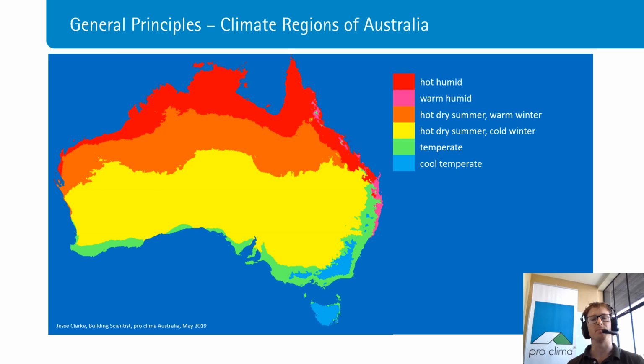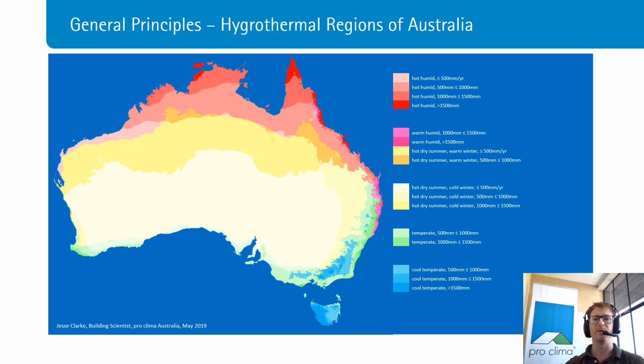So we need to understand the properties of the materials used to weatherproof our buildings to make sure that we don't trap moisture or create high humidity within our construction systems. When you overlay those two things, the combination of external moisture, how much it rains, and the internal conditions in the building, whether it's heated or cooled and whether it's dehumidified, and the water vapor pressure or the amount of humidity in the building will all affect how we need to design the building envelope systems, including the insulation, to make sure that we can have dry, healthy, durable, and energy efficient buildings.